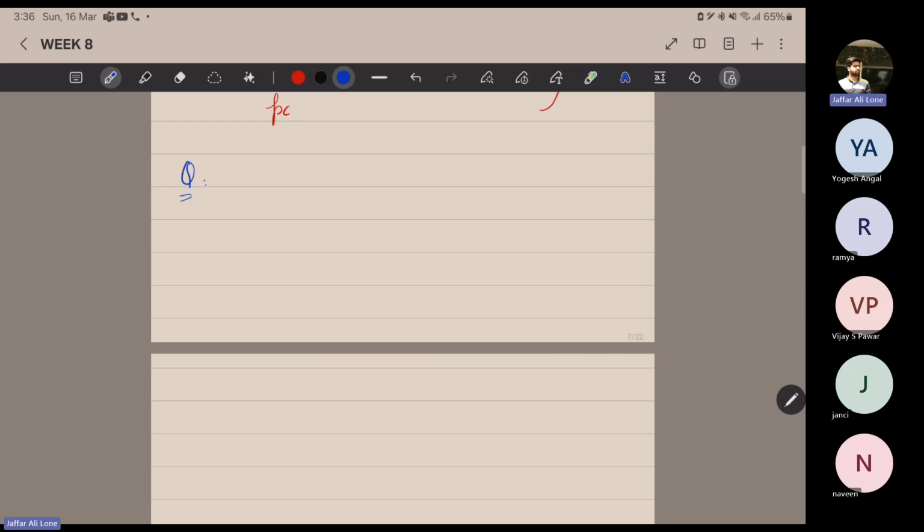But if you place them close to each other or far away from each other, not that close, then maybe you do not get a second order system, but the formulas you have for the overshoot and settling time are only designed for second order systems. So in that case, your calculations will not be that accurate. You'll be close to what you want to achieve, but they will not be accurate. So this all will come if you practice this in MATLAB. But yes, we can place poles and zeros exactly the same, and we'll see that in later examples.